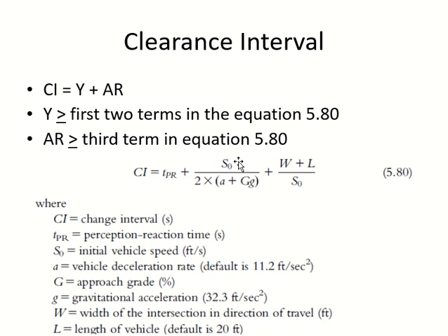So we took the equation of stopping sight distance divided by the speed to get the time. So this is for those guys who are exactly at the stopping sight distance from the signal. So we consider it a dilemma zone. So these people decide to go. So during yellow time they will reach the stop line.